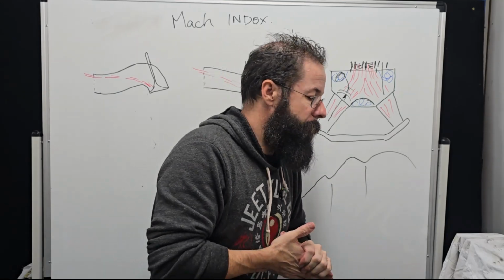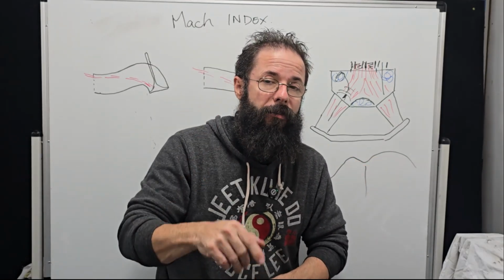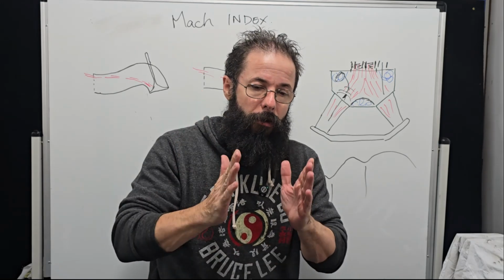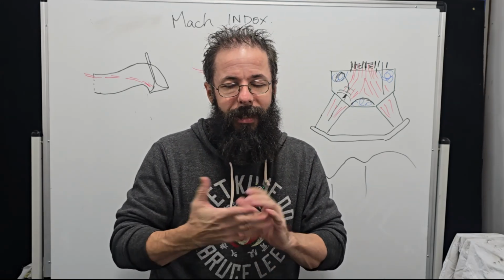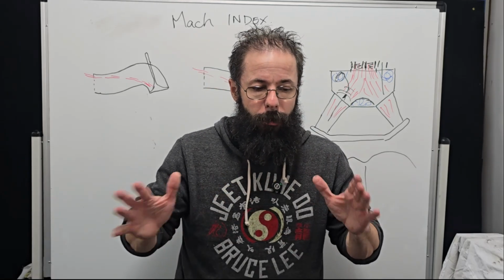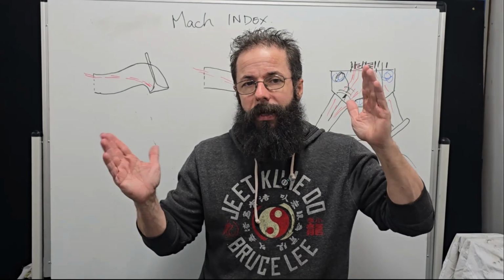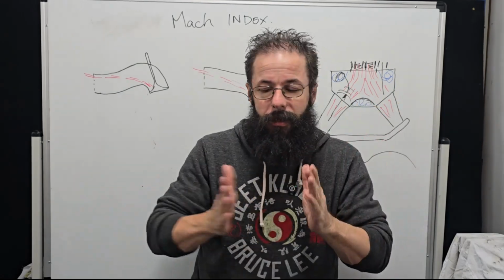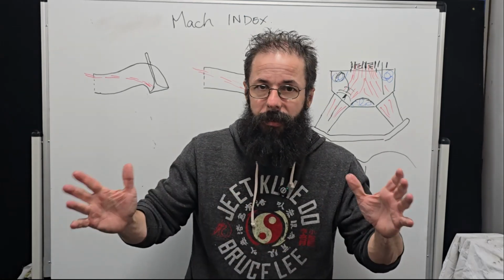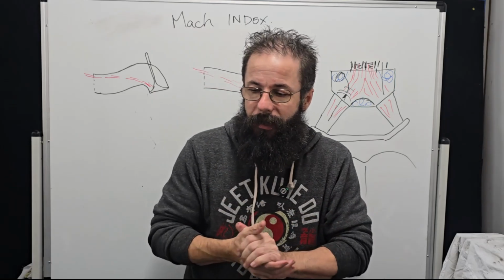So, all right, I'll get this cleaned off, and then we're going to go into some 4-valve stuff and cover a couple of things. I want to cover the parallel runner versus tapered runner, because I see a lot of dyno tests out there. And again, I don't like to say people are doing things wrong, but in induction we need to understand the whole picture, from the air cleaner to the tailpipe, because every part affects every element in the system.